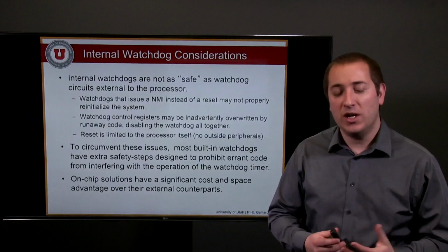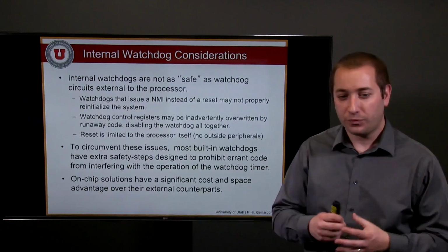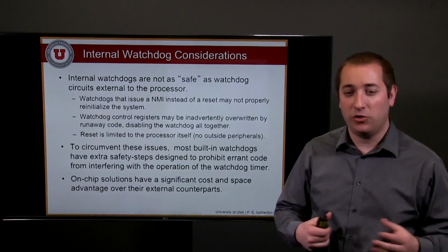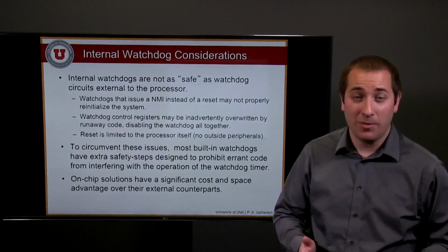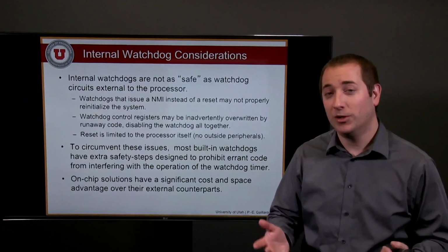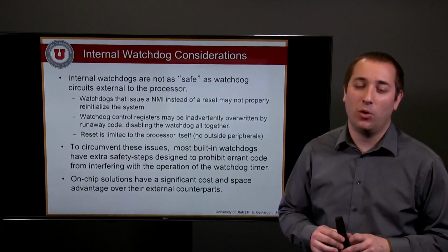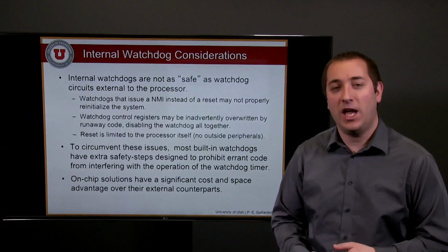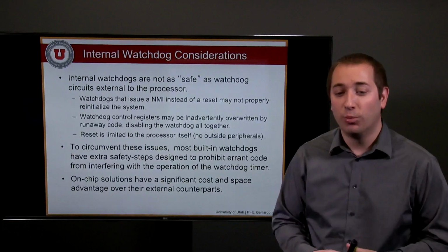Of course it is not as safe as a fully external circuit, because your watchdog might actually suffer from hardware issues in the processor. If the NMI is not responsive, your watchdog will not trigger anything. You might have errant code that overwrites your watchdog when it should not. And the reset is limited to the processor itself; you are not resetting anything else on the board.